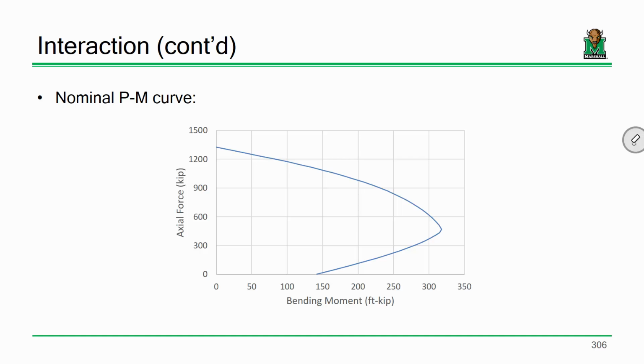But if we're talking about just general building design and general elements, certain levels of compressive force can actually serve to increase the bending capacity of a given section. Why is that? Concrete is a material that is very, very strong in compression, but very, very weak in tension. And what you're doing is taking this member and putting more compression on it. You're putting the force on it that concrete loves. Okay? Does that make sense? So that's why it behaves better.